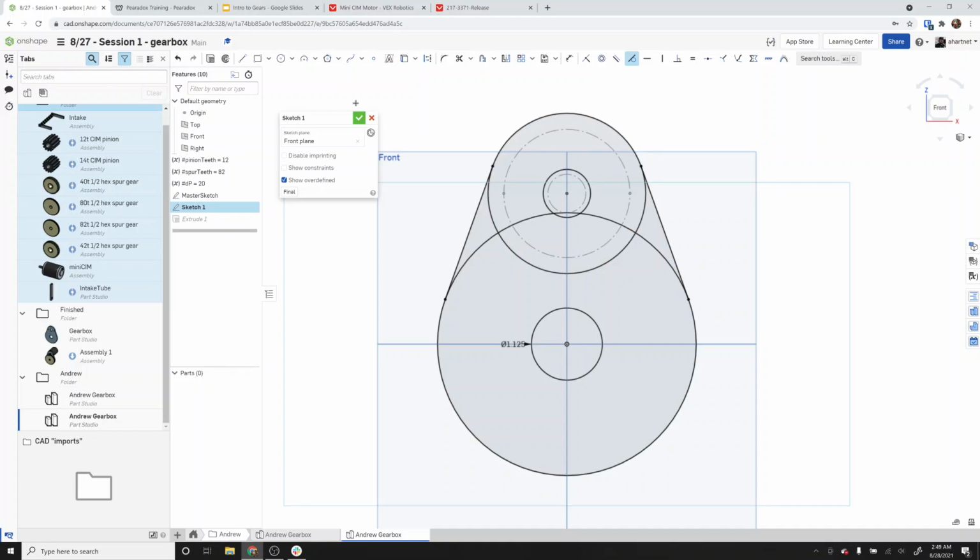The next thing we're going to do is take advantage of this trim tool. So again, M is the shortcut because it's in parentheses, but we just need some of these lines on the outside. If you've noticed when I was doing the extrude, I had to select multiple parts because there are multiple enclosed areas. So I can use the trim tool, and these things that are inside, I can trim them.